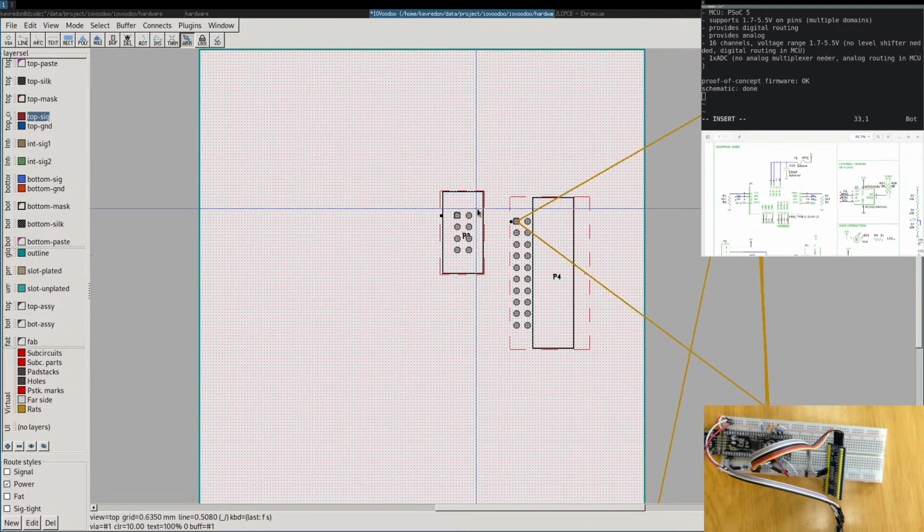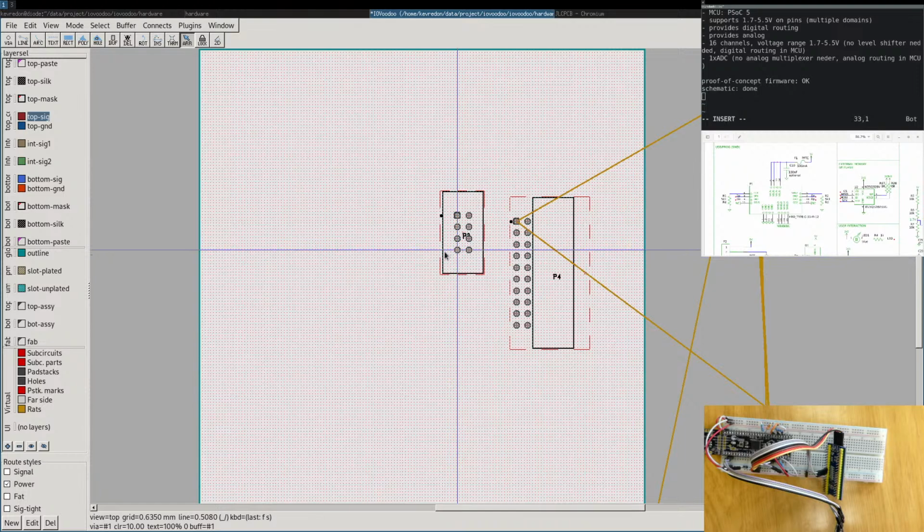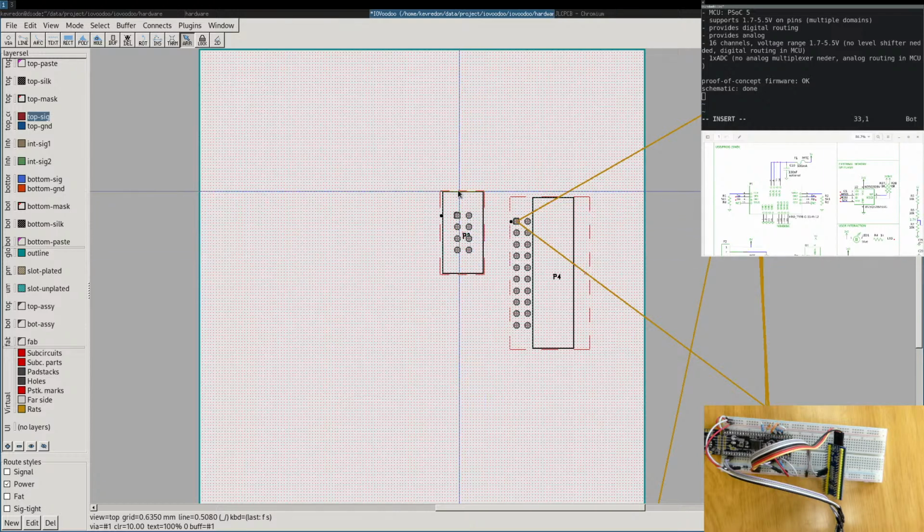I use this connector because if I don't have any through-hole pin, I have a lot of space, and if I don't have enough through-hole pins, I could use something which is boxed, a shrouded header pin. But this shrouded header pin is far too large. I will probably change it and have just a connector to it. For now, let's put it this way.